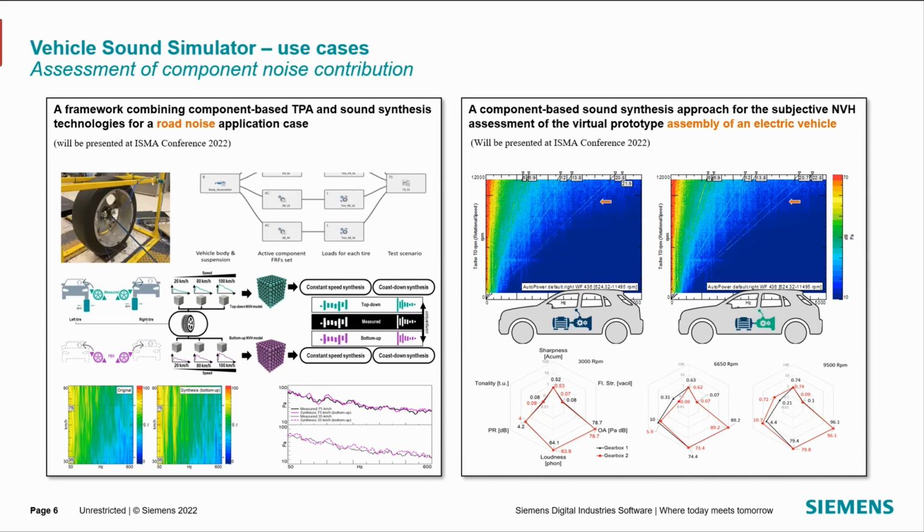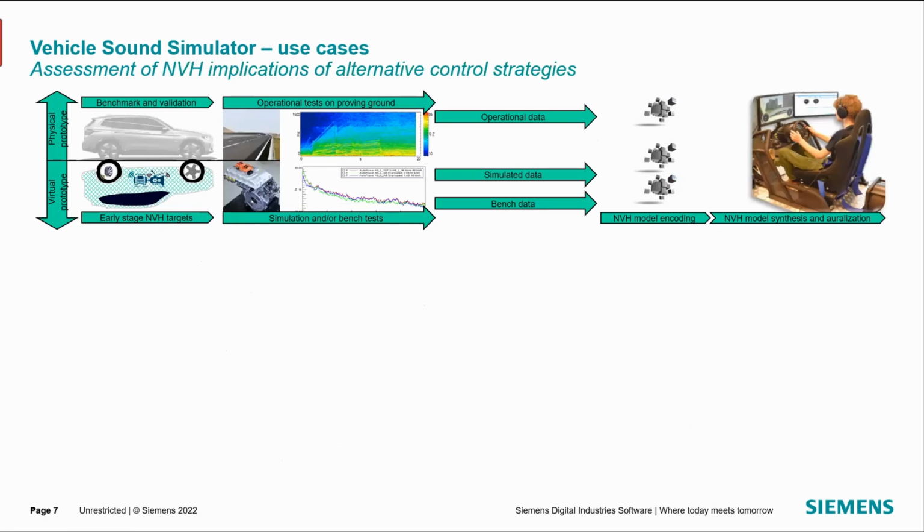With the same principle, we are able to act on our digital version, so on our executable digital twin, and replace virtually the gearbox and assess realistically what is the sound produced by the gearbox next, and also in combination with all the other contributors to the sound, so the background noise, the wind noise, the engine noise, electric or combustion engine noise. And this leads not only to a subjective assessment, but also, as you can see, to a set of measurable and objective quantification of this type of quantities in a fair comparison.